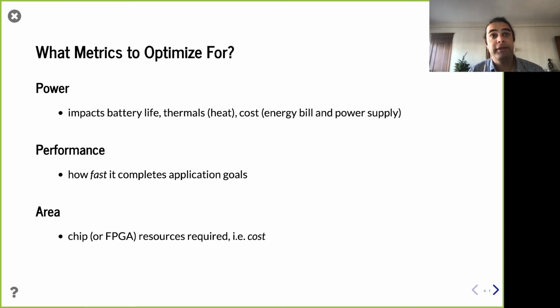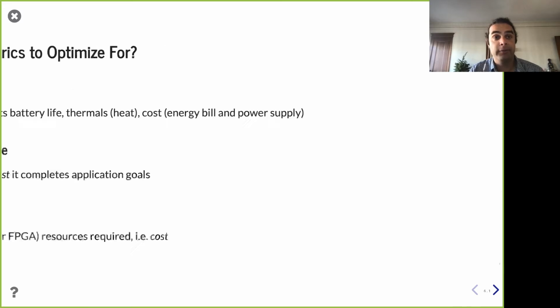So these are all three important metrics. As I mentioned the last time I brought up PPA, sometimes in software we're only worried about performance or maybe memory usage, but we definitely don't worry about power too often in software, and we usually don't worry about three metrics simultaneously. Like if you have an application that is compute bound, you're really worried about performance. Memory capacity usually isn't the problem, or if you have a problem that's really capacity bound, then usually performance isn't the problem. You'll find for hardware that you're commonly hammering on all three of these at the same time. If you want to improve one, it's going to cause issues in the other two. You're going to need some sort of trade-off. We're going to talk about exploring those trade-offs next week. So you usually have this more complicated optimization goal of having three things to optimize for.